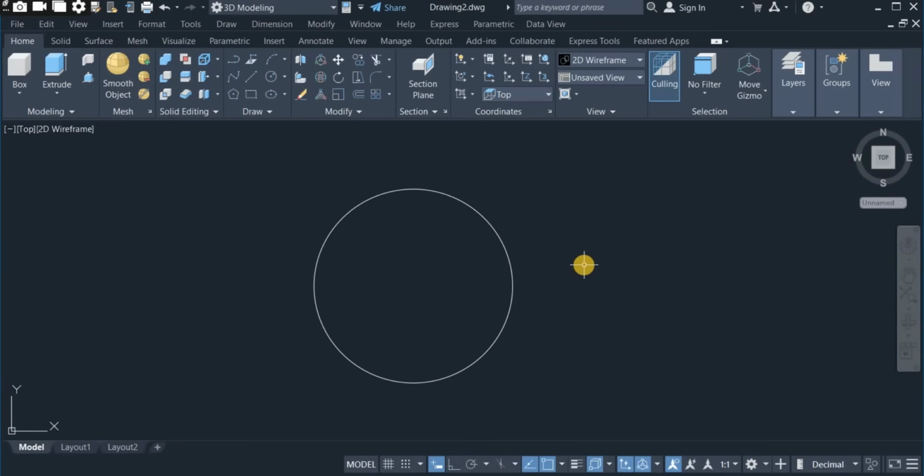Okay, so I'll now design the tooth profile, and from the parameters I have, the tooth thickness is 3.925 and the tooth depth is 5.625. So I'll draw a rectangle of 3.925 by 5.625.